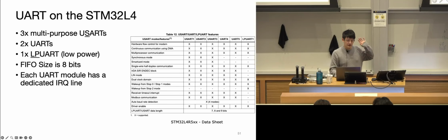And each of these UART modules has its designated IRQ line, so that whenever there's data that comes in or data that needs to go out, there is going to be an interrupt signal that's pulled up to the core.